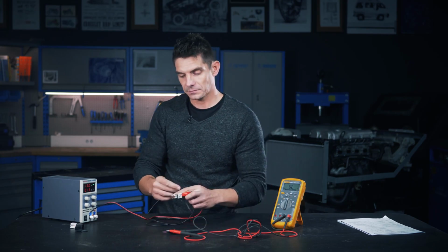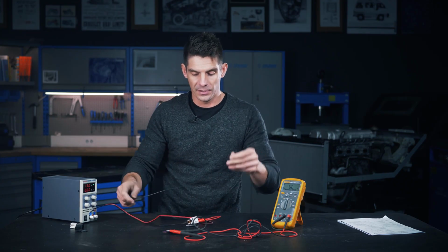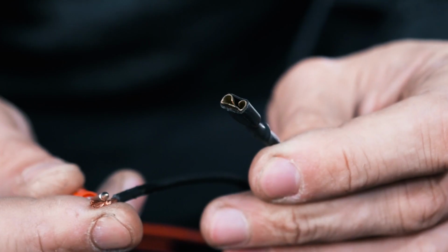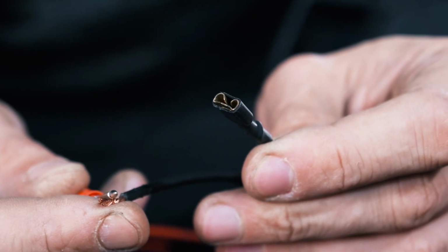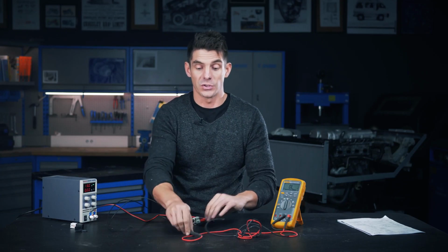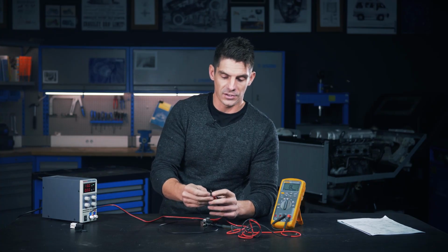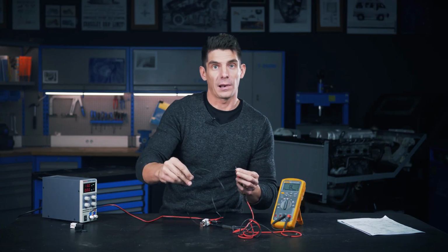There we go. Always a useful tool for diagnosing these things is to make yourself up a lead which has just a spade connection on the end of various different spade sizes, so you can plug into terminals and you're not, as I was doing there, attempting to balance these things around. Much more logical, if I was feeling intelligent, to attach this to here and then apply that to the spade.